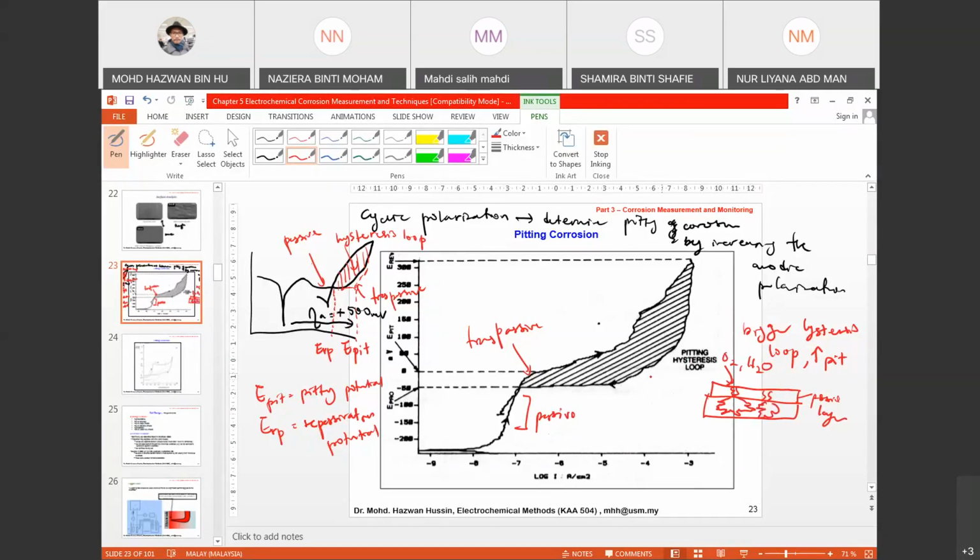So when you have a pit, this is where you have a response of transpassive. Okay. And repassivation actually happens when there's a passive layer forming inside your pit. Repassivation means the formation of a second passive layer, and the second passive layer forms at pitted metals.